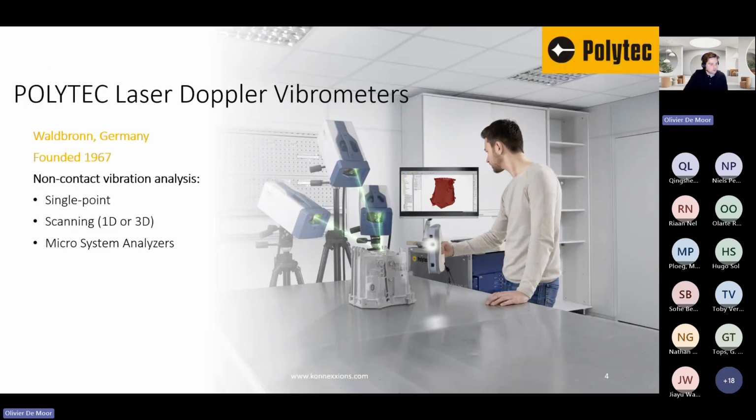So Polytech is a German company. They're located in Waldbronn, and they are already existing since 1967. So they have a lot of experience in the production of optical measurement solutions, but today we will only focus on laser Doppler vibrometry. There are different types of laser Doppler vibrometers. The single point laser vibrometer is just a point and shoot method. So you point your laser beam to the target that you want to measure, and you can get directly the vibration information of the point that you measure with your laser beam.